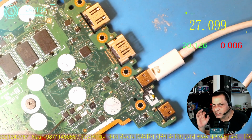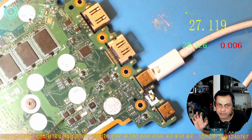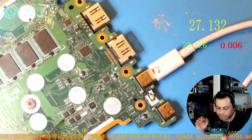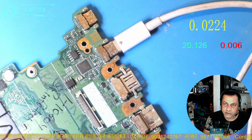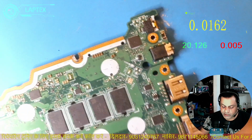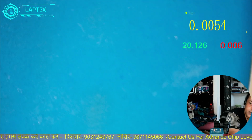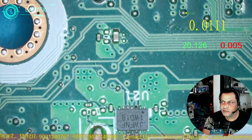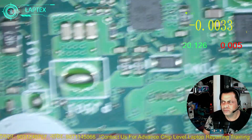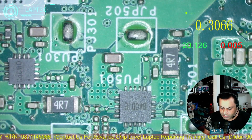It means my PD controller is 100% alright. My translator IC is 100% alright. The only thing is that maybe the problem is in the charging IC or somewhere else. For example, 3.3 and 5 volt is required. So you can also repair like this. You need not have a diagram like that.